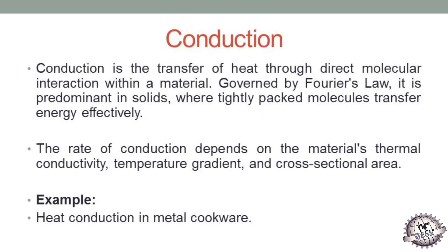So, the first mode of heat transfer is conduction. Conduction is the transfer of heat through direct molecular interaction within a material. Governed by Fourier's law, it is predominant in solids where tightly packed molecules transfer energy effectively. The rate of conduction depends on the material's thermal conductivity, temperature gradient, and cross sectional area. For example, heat conduction in metal cookware is the best example of conduction.